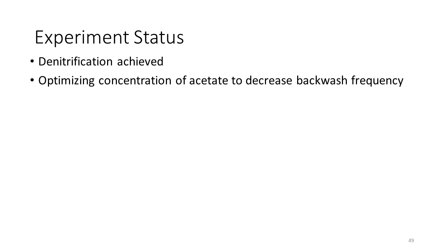So it's going to be specific surface area. I think that's one of the key parameters. Yeah, there are 3 scaling criteria. You probably want to have the film diffusion not be limiting, so you have the Reynolds number high enough to not be film diffusion limiting, and then whatever the next process is that's governing, which in RSSCT is internal diffusion within the media. That's not it here, it's the biomass uptake, so it's got to be specific surface area. That makes sense. Thanks.